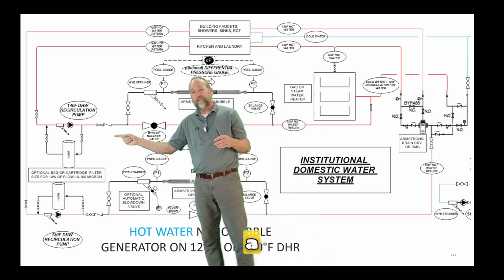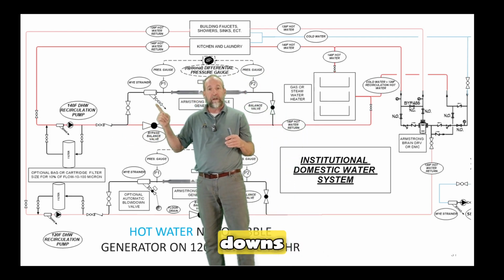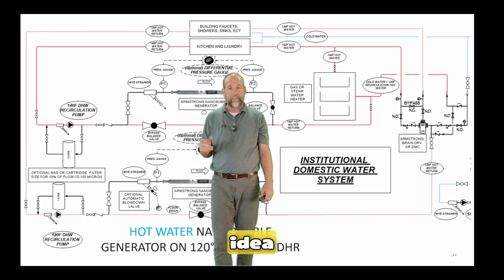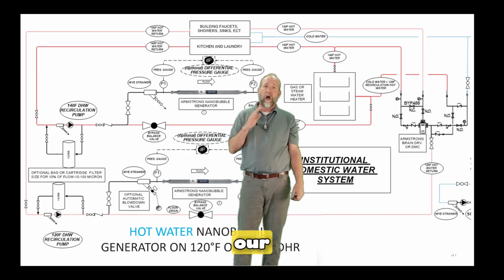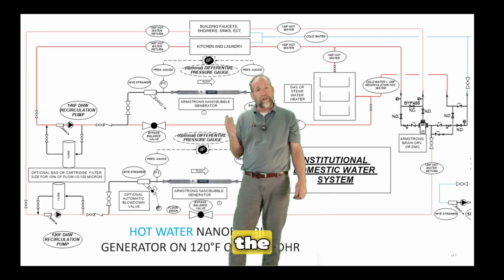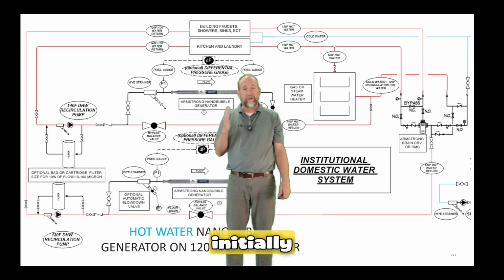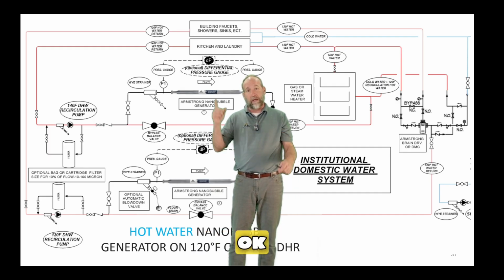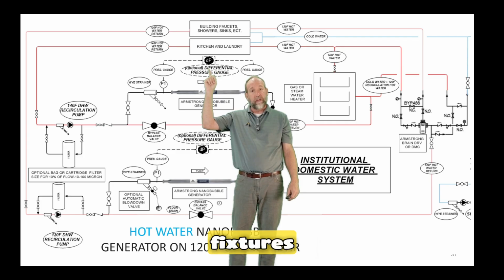Having these filters is a really good idea. Doing your blowdowns is a really good idea. Having your automated blowdowns is a really good idea. I will tell you that our experience over the last couple of years of starting dozens of these up and working with customers has told us that one of the best things you can do, when you initially start these generators up, is to do a lot of blowdowns. Whether you're blowing down your plumbing fixtures out in the system, that would be good.